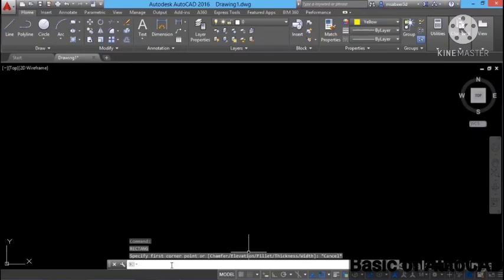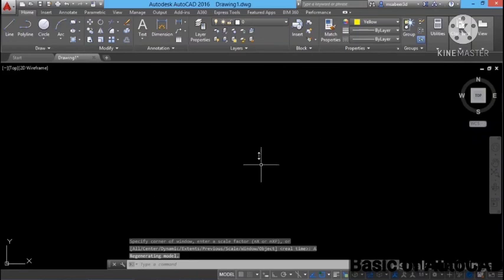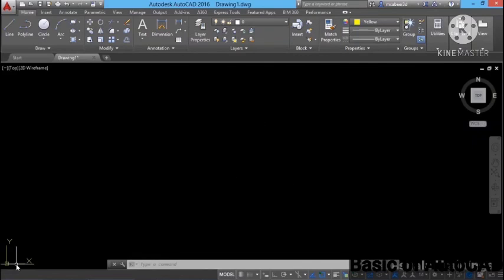So let's give the limits command in AutoCAD to get these limits on the screen. I'll give limits, and for the lower left, when I'm asked, I'll give minus 60, minus 60. And for the upper right, when I'm asked, I'll give 60, 60, followed by Z for zoom, and I'll type the letter A, or I'll click on all to get the limits on the screen. Obviously, all the 4 quadrants must be in the screen, but the origin still remains here.